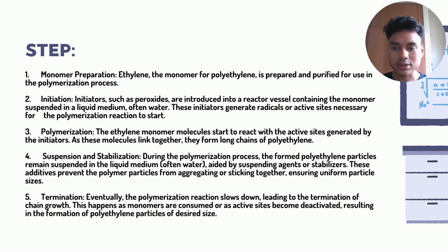Fourth, suspension and stabilization. During the polymerization process, the formed polyethylene particles remain suspended in the liquid medium of water, aided by a suspending agent or stabilizer. This additive prevents the polymer particles from aggregating and sticking together, ensuring uniform particle size.